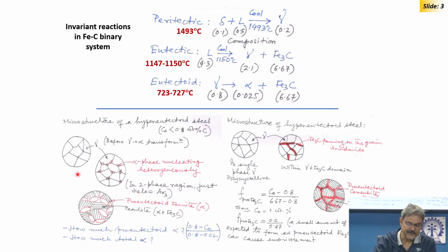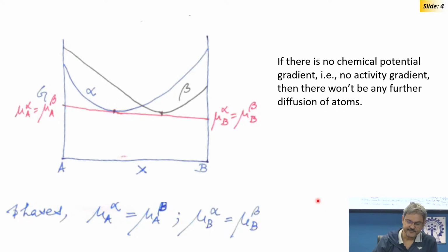Otherwise, as I have already said, you either go for pro-eutectoid ferrite and then pearlite. Pearlite is a eutectoid product of ferrite and cementite. Typically, it is of lamellar structure, but the structure may change. Another problem in hypereutectoid steel is the grain boundary cementite network, which affects the properties and makes the structure brittle. So, we think about how to avoid it, apart from pearlite in the middle.